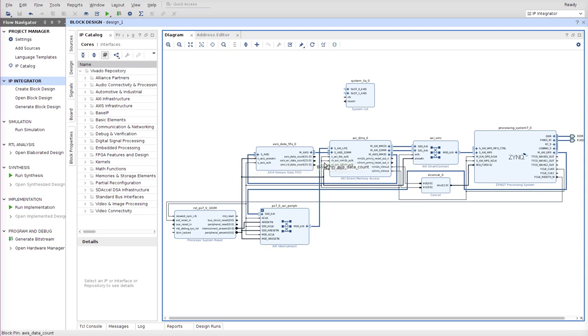So that's why the first one for our FIFO, we're gonna check these two ports. We're gonna check when the FIFO gets data and when the FIFO transmits the data. So it gets the data from the slave channel. Basically, the DMA is gonna write the data to the FIFO and then process, and then the FIFO sends back to the DMA via its master channel.